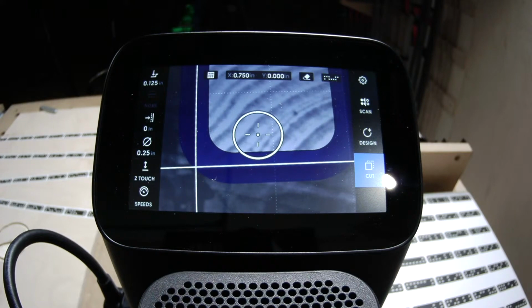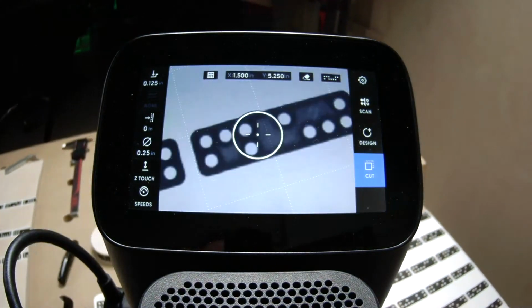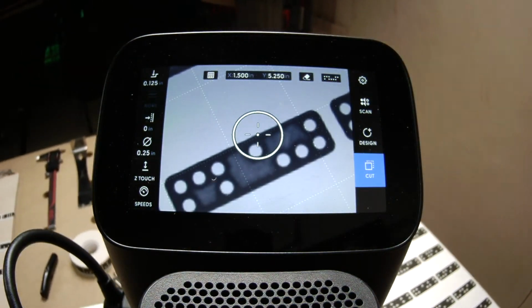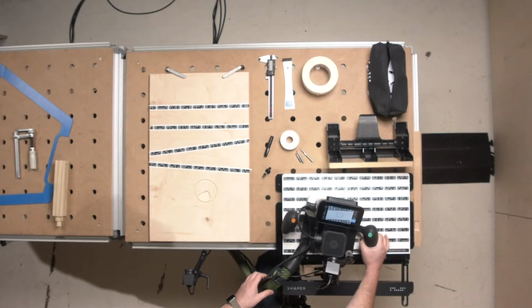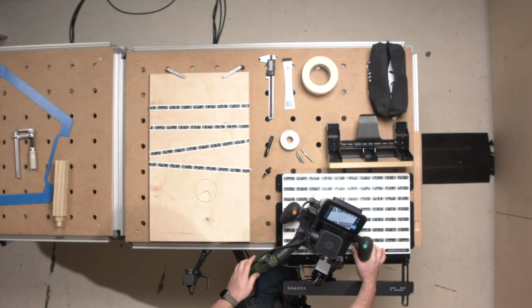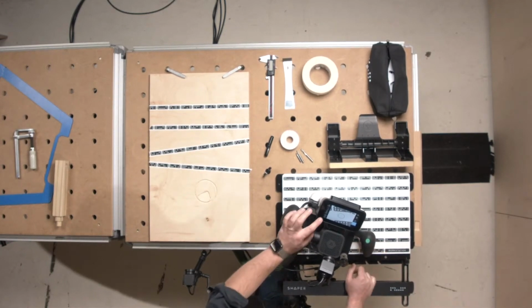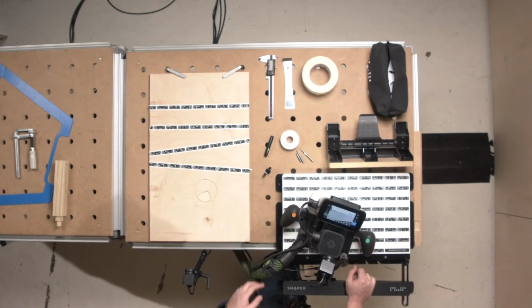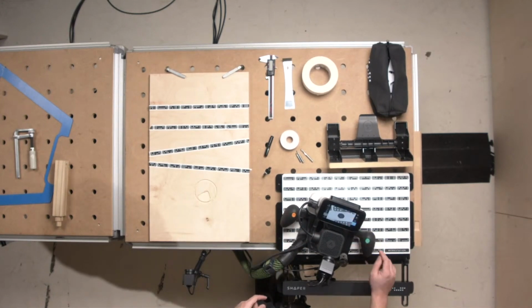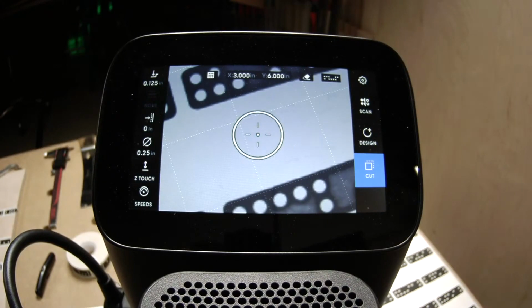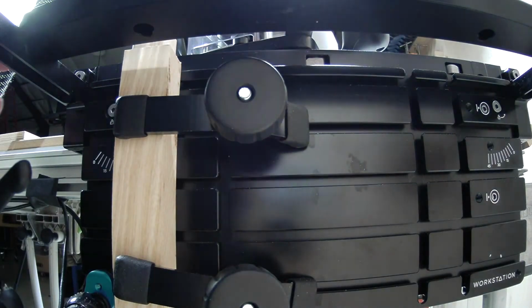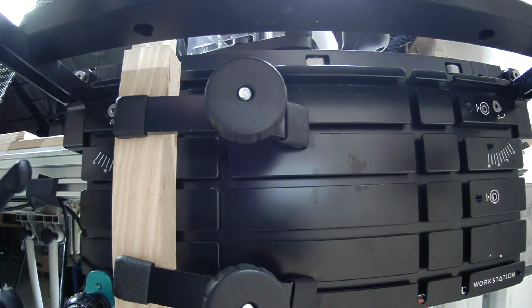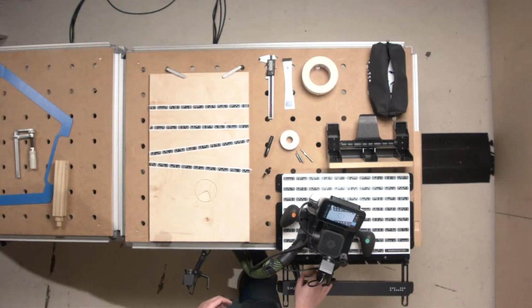It's also okay in this particular case with Workstation to just go ahead and move, if you go back to the top view, Eric, move Origin onto just the shaper tape area of Workstation. As long as shaper tape is in view, Workstation will be able to touch off. So I can, again, tap on Z-Touch, and Z-Touch is successful there. And because we use the support bar to set the tenon up, I know that the top surface of the tenon is matching the top surface of Workstation, so I'm not super concerned about differences in height there.